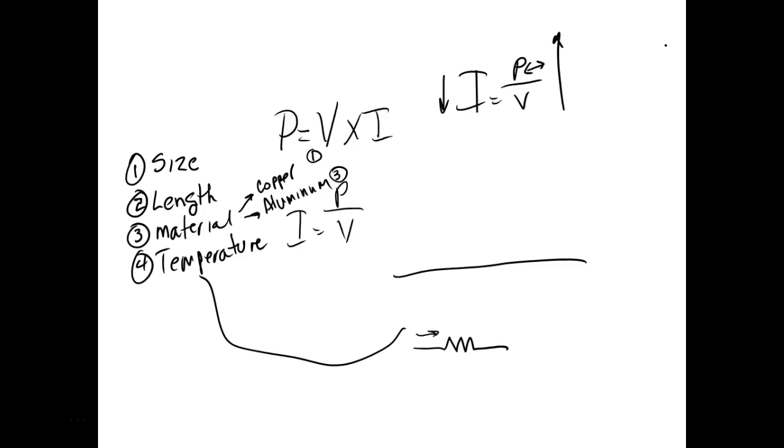So DC, I could have my battery out there as a DC supply, and that sucker's probably got 200 or 300 cranking amps available to us. But look at the gauge wire you have running from your battery down to your starter. The wires running into your cockpit are not near as big because they don't have to be. So the big current puller in a car is that dang starter out there, and that's where the big wires are. Why do they have to be so big? Because the voltage is so low, right?